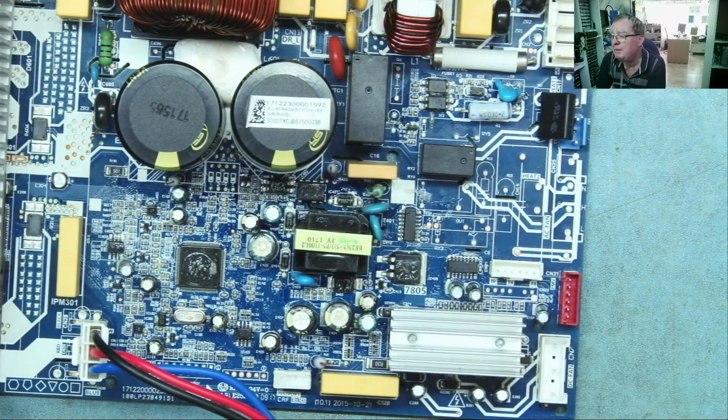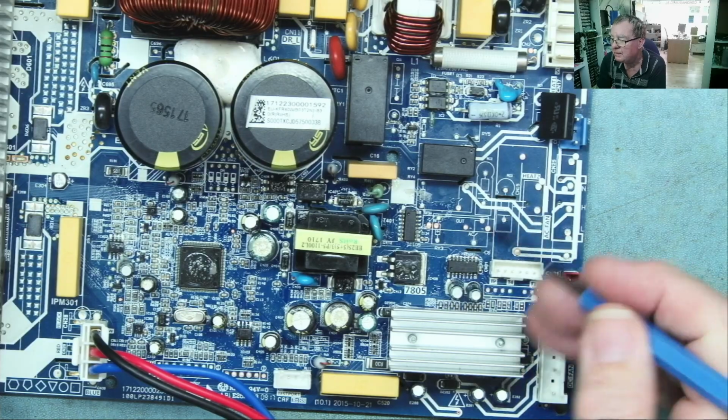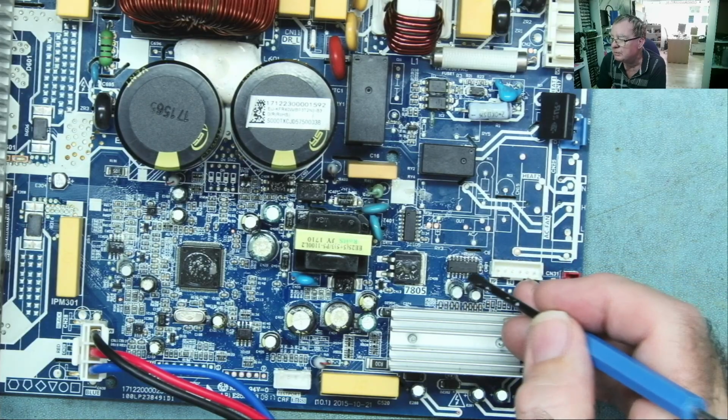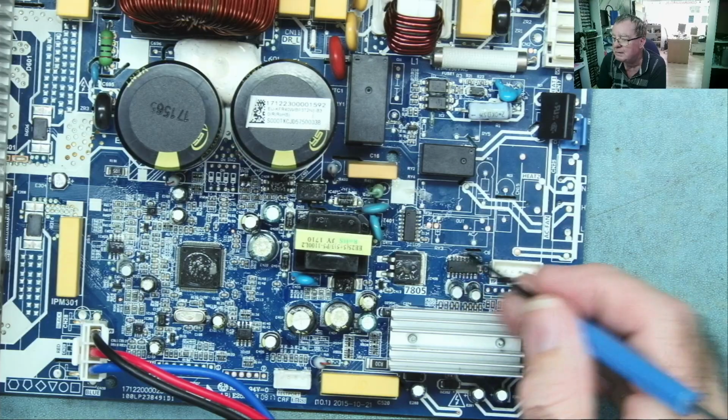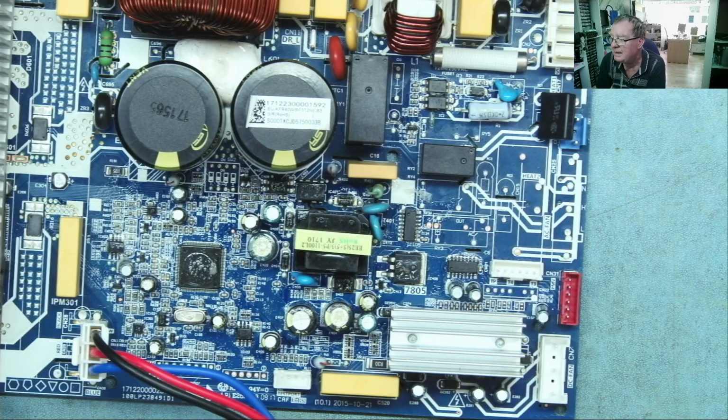But those type of chips are prone to failure. The only way to be sure probably is to just replace them if they're cheap and easy. You may be lucky and find the thing has a hole in it, something like that. You may also be able to measure from all the inputs to ground and all the outputs to ground and see if you can see one that reads different from all the others.